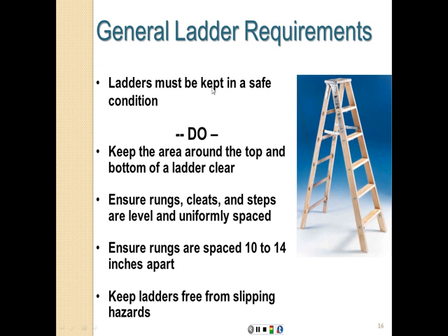General ladder requirements. Ladders must be kept in a safe condition. What do we mean by a safe condition? Keep the area around the top and bottom of the ladder clear, again to prevent tripping and slipping. Ensure rungs, which are the steps of the ladder, cleats here at the bottom, and steps are level and uniformly spaced.